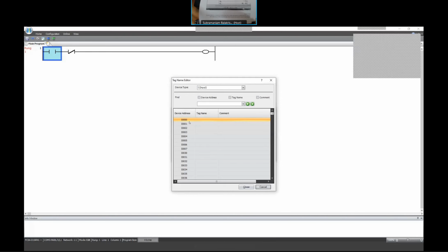Then if you add additional modules, it doesn't start as 8, 9, 10. It starts at 30. 30, 31, 32, 33, 34, 35, all the way to another 8. Then it'll jump to 40 to 47. Then 50 to 57. 60 to 67. Why this kind of a numbering system? Well, these are all digital. It is a binary representation inside. So don't question, right? So I'm going to choose the first input, I0, close.